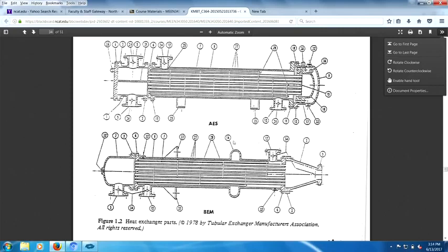So when you're manufacturing heat exchangers, there's probably 4 hold points. What the devil are hold points? Well, if you're going to build one of these things from scratch, you've got to figure out exactly how you're going to pick a vendor and whether you can trust the vendor. So there's 4 hold points for heat exchanger building and construction. First, you want to visit them just to get acquainted. You want to see if their welders are actually certified, look at their welding capabilities, look at their background, see if they actually know how to weld.